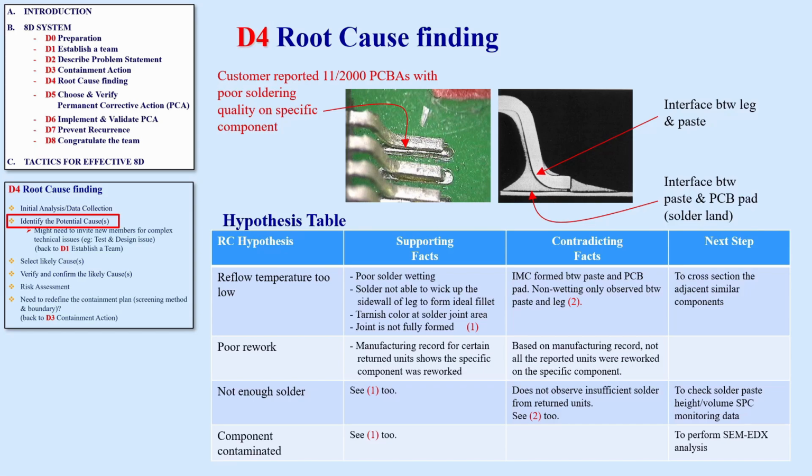The last hypothesis here is component contaminated. The supporting facts are the same as low reflow temperature. To confirm if the component is contaminated, we can perform SEM-EDX analysis. The beauty of the hypothesis table is that it will visualize all the facts on a single table.